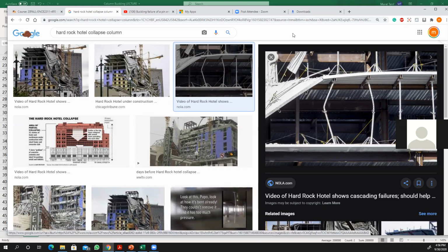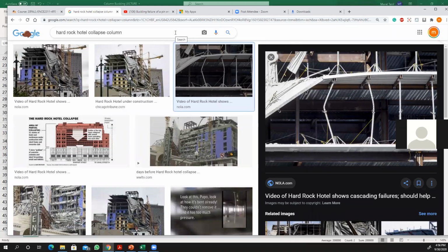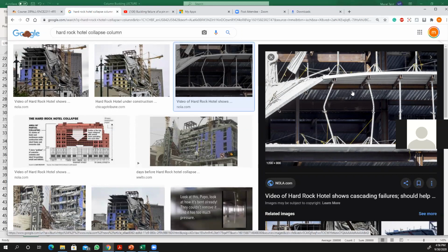That's cool. This is the big picture, okay? You have to know the load path, how the load is flowing from the roof to the bottom. And then you can size up your girders and your interior beams. These are interior beams, by the way, right here, and you have your girders, bigger size beams. So the load from the slab is carried by the metal deck, and then it is transferred to these interior beams, from interior beams to girders, from girder to the column, the big column. You have a big column right here.